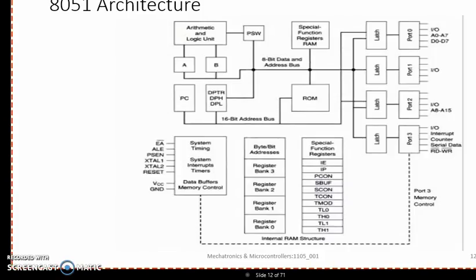Figure shows 8051 architecture. The 8051 architecture consists of three specific features. These specific features: 8-bit CPU with register A, the accumulator, and B, 16-bit program counter and data pointer, 8-bit program status word, 8-bit stack pointer, internal ROM of 4 kilobytes, internal RAM of 128 bytes.